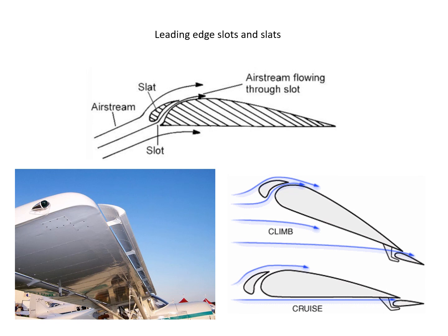As that video showed, if fluid is pushed tangentially into the boundary layer, it reduces negative pressure gradients and reduces detachment. It impairs detachment. And one way to do that is seen here. This is called a leading edge slat and slot. So the slat is running the chord length of the wing. So the chord is the distance from where the wing attaches to the body fuselage and out to the tip. That's called the chord.